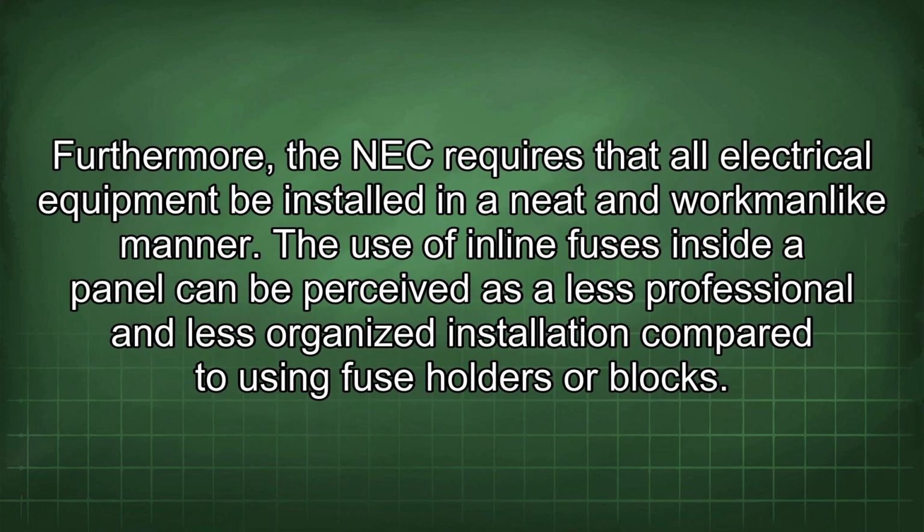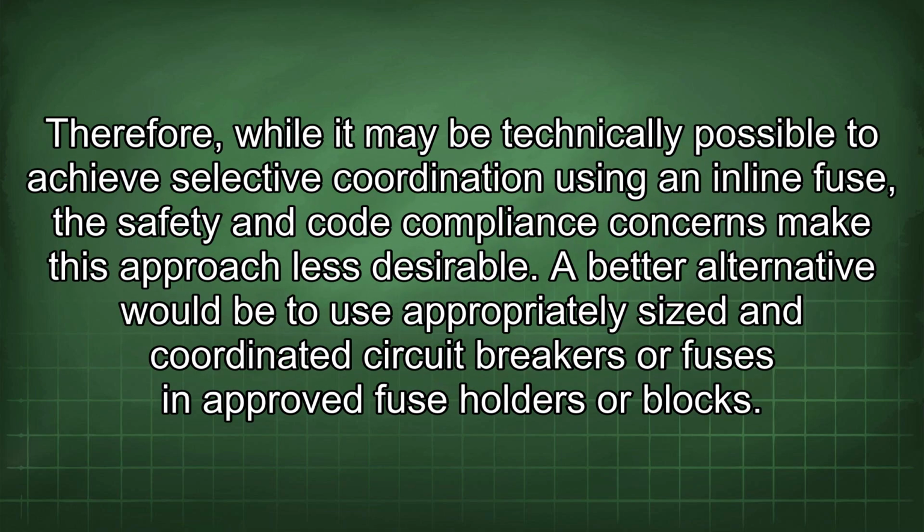Furthermore, the NEC requires that all electrical equipment be installed in a neat and workmanlike manner. The use of inline fuses inside a panel can be perceived as a less professional and less organized installation compared to using fuse holders or blocks. Therefore, while it may be technically possible to achieve selective coordination using an inline fuse, the safety and code compliance concerns make this approach less desirable.